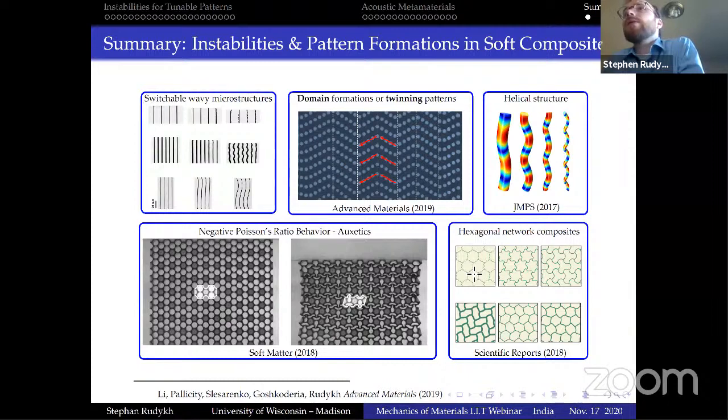Again, what drives these wavelengths here is your choice of the thickness ratio between the matrix and the stiffer layer, and also the contrast in their properties. Because these two parameters define what the wavelengths will be, you then choose the right thickness, depending on what you want, and then you can observe these wavelengths close to what you expected, and basically that's the whole idea behind it.